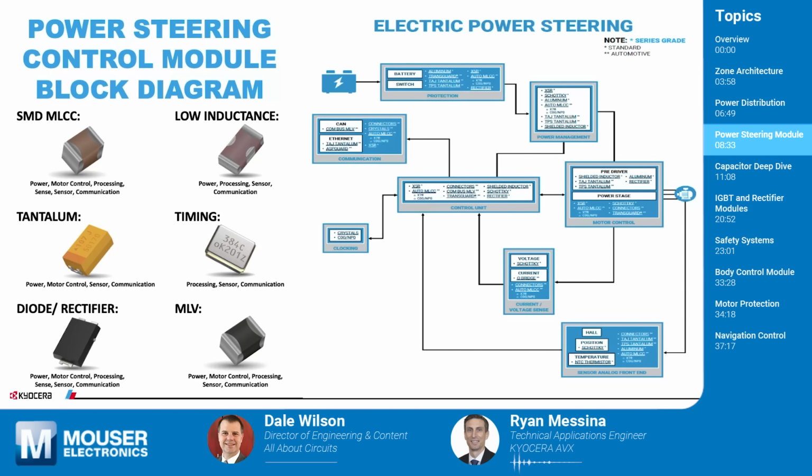So if we just changed the formula on the dielectric on one of the caps, we would then have to notify you or the manufacturer of the change. And then you might say, well, hey, I'm not cool with that. I would like to have some batch testing done, get the electrical data and try to see what's going on. If you have an automotive quality part, you're going to get all of that data and you're going to have that sequence of events of what's happening with the part. If it's just a commercial part or standard part, you won't have any of that industry-wide. So if you go with the standard part, you're really kind of rolling the dice.